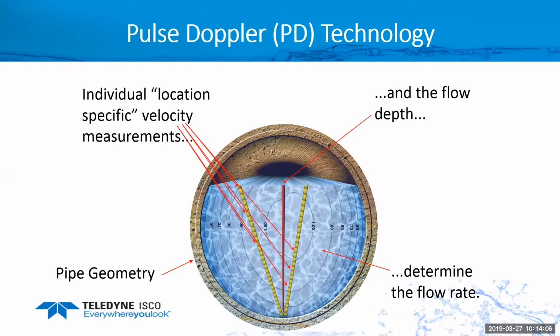The level measurement is actually done by an upward-looking ultrasonic. So instead of my example earlier, where we were shooting the sound wave down on the surface of the water and bouncing back, now we have a submerged Doppler signal shooting upward, hitting the surface of the water from underneath and coming back. So there's our level. Knowing the geometry of the pipe, its size and shape, with the level that's in the pipe, there's our area. Times that by our velocity, and there's our area velocity.